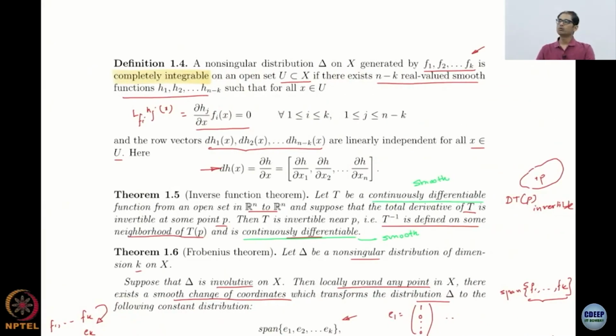Now we actually move on to the statement of the Frobenius theorem itself. Why do we care about the Frobenius theorem? Because we are trying to answer that original question. When is it possible to feedback linearize a system, completely feedback linearize a system? Until now we have been looking at relative degree which is less than n. Of course the Frobenius theorem is useful even then, but it becomes especially useful to figure out when your relative degree can be made n, okay, which means that you essentially have the entire system look like a linear system, after suitable state transformation, okay.